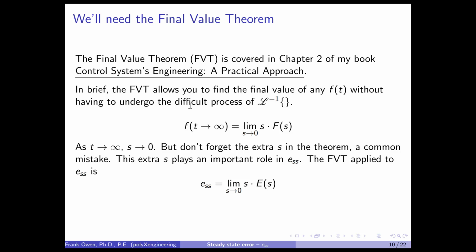To analyze this, we're going to have to use something called the final value theorem, and this is covered in chapter 2 of my book, which is focused on the Laplace transform. But anyway, the Laplace transform is a tedious analytical way of converting from the time domain into the S domain, or converting differential equations into algebraic equations. And the problem with that system is you convert your differential equations into algebraic equations, you solve the algebraic equations, and then you have to reconvert back into the time domain. And that process of converting from the S domain back into the time domain is called the inverse Laplace transform.